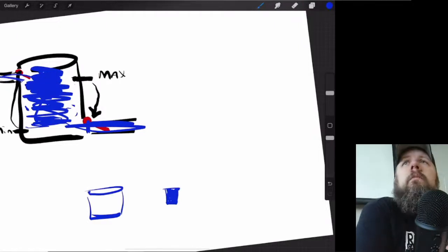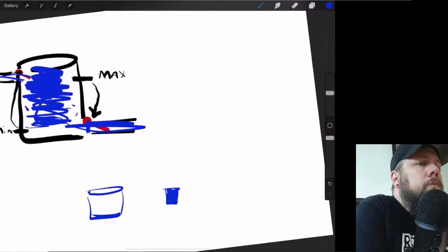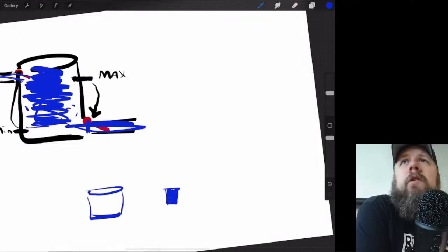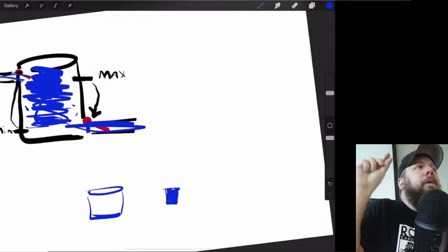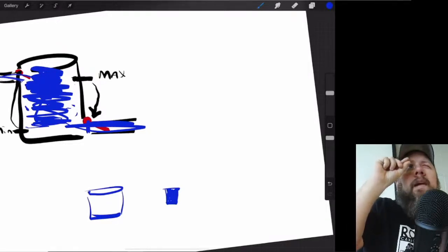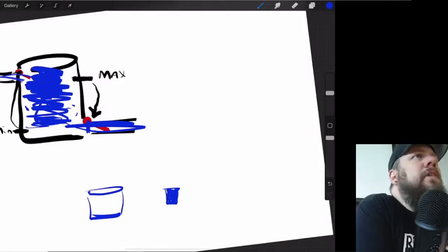Do y'all feel like you understand what that 555 was doing? It was charging up and discharging the capacitor that you put in it. And the faster it did that, the higher the frequency of the tone. What happened when a couple of y'all put a 5 or 10 picofarad, one of those little ceramic, gray or beige looking capacitors that didn't have much capacitance?